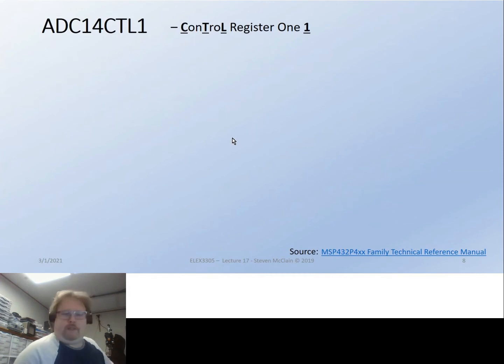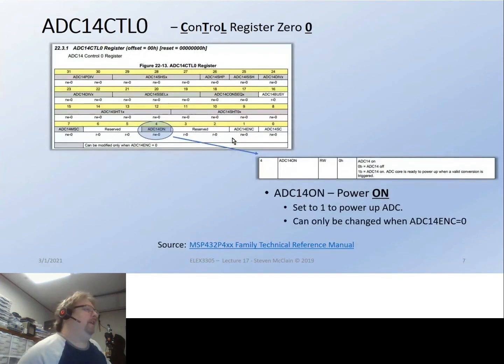So those are the important ones out of that whole register, right? After looking at all that, the rest of this stuff is setting the sample and hold times and setting the clock dividers and the clock sources. I guess there's a busy flag in here we might care about a little later. But if you look at what the rest of this register is doing, it's mostly just setting up the clock and all that stuff. Does it pick a clock to start with if we don't set one? It's got like a preset.